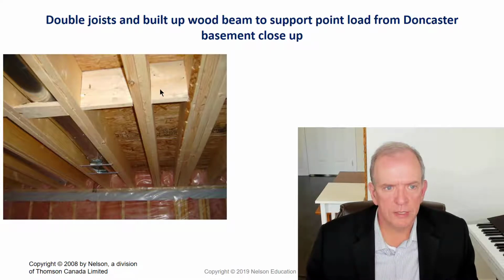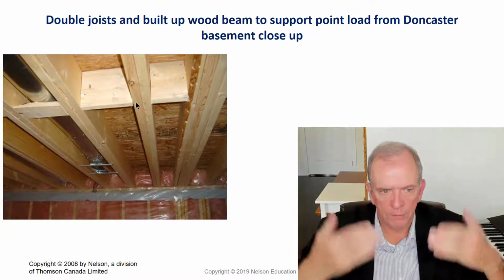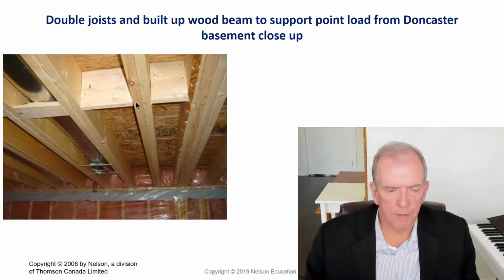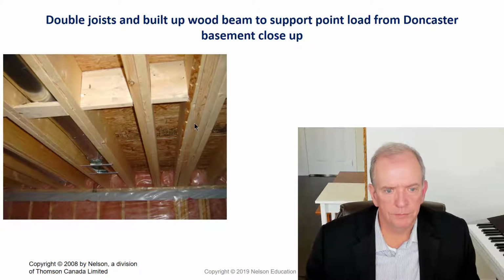And this is what we call solid bridging. It's solid lumber that goes in between the joists, and it really strengthens the floor against deflection when you actually walk on it from up above.